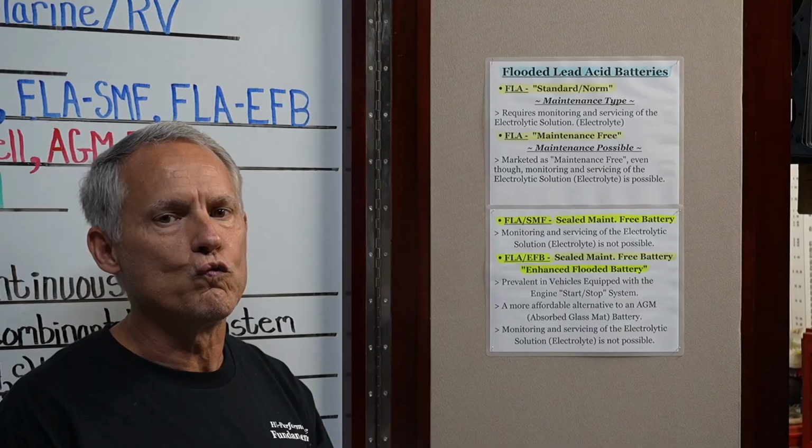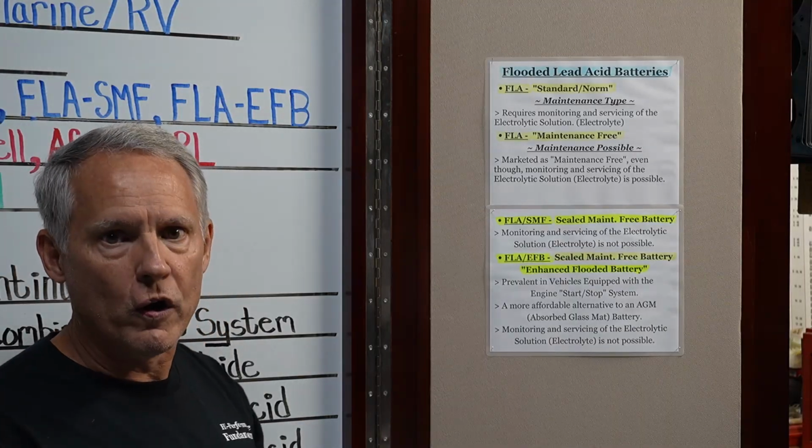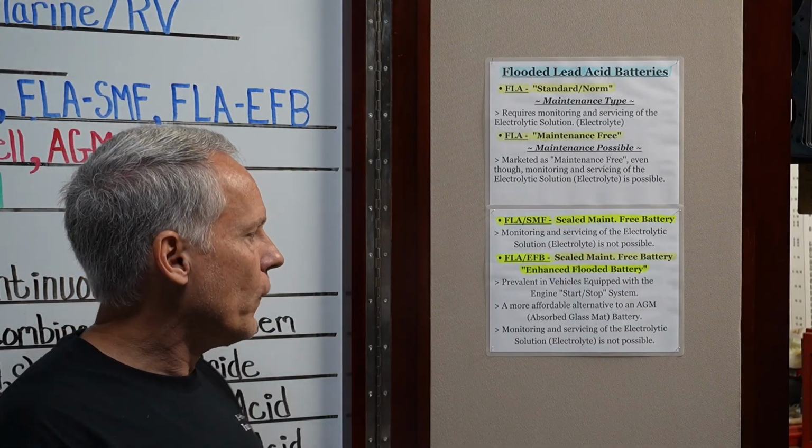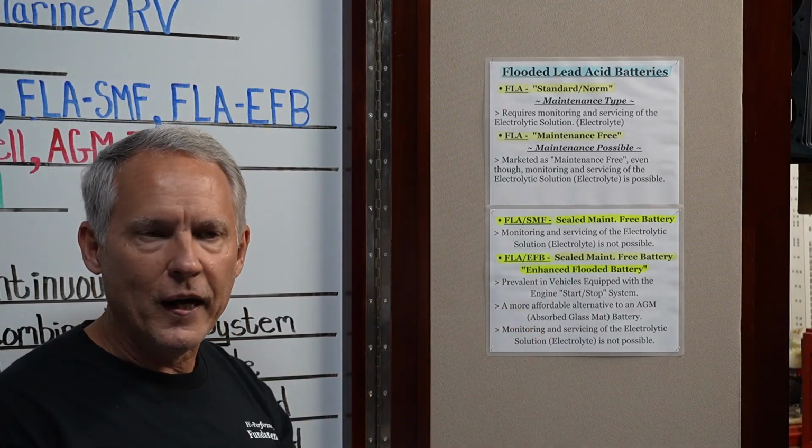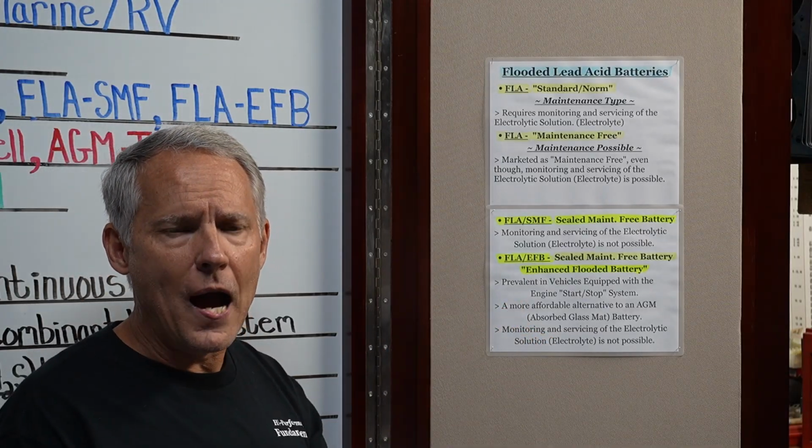It's got to be able to recharge rapidly, or the battery's going to end up discharged and dead before you know it. So they are designed differently internally. You'll also find them on vehicles with regenerative braking, like mild hybrids or hybrid electric vehicles.